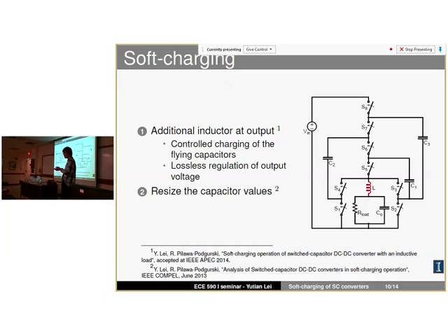Also, because this port now has very large ripple, your buck converter has to try really hard to get a steady DC voltage at the output. You have to use both feed-forward and feedback control. It's very complicated. Here, we actually switch all of them at a medium, pretty fast frequency, so we only need an inductor.